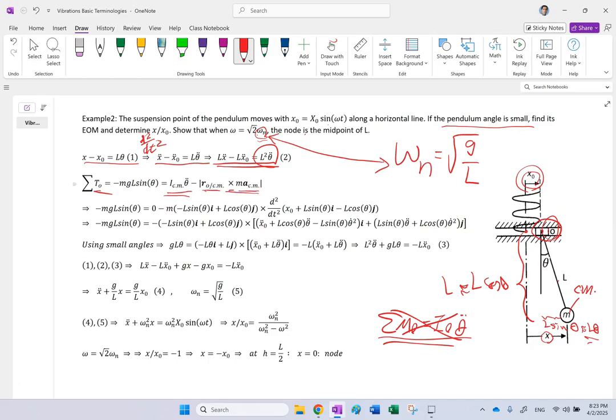This is your inertial force. That vector here is from Cm to O, so that is this vector here. That is R of O with respect to the centroid. I need to cross that vector with m a Cm, and this is only going to be in the K direction, as well as, of course, I Cm theta double dot, which is going to be in the K direction out of the board. And the sum of the moments about point O is also going to be all about K. So everything is going to be along the K axis out of the board.